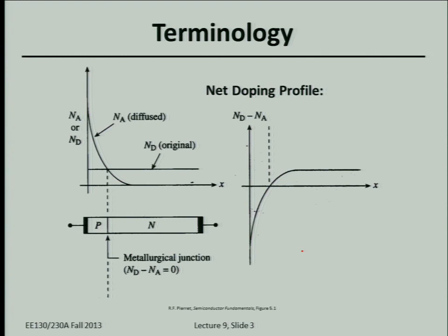Okay, so as you know, in reality, when we form a p-n junction diode, there will actually be donors and acceptors on one or both sides of the p-n junction. In this class, just to derive the simple equations to tell you how the voltage is dropped across the junction and how current flows, we just ignore that. We just assume that we have a p-n junction. The p side is doped only with acceptors to a concentration Na. And the n side is doped only with donors to a concentration Nd. Okay, so this is just to simplify the equations.